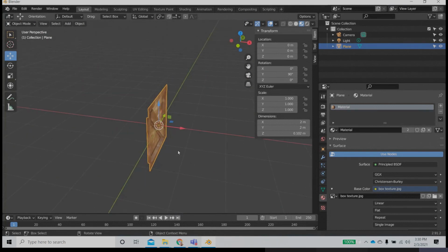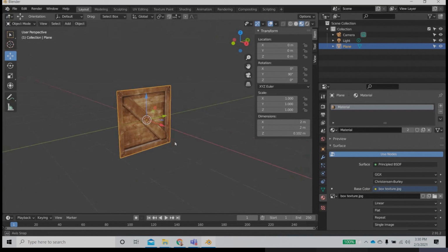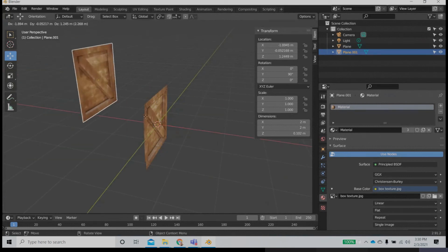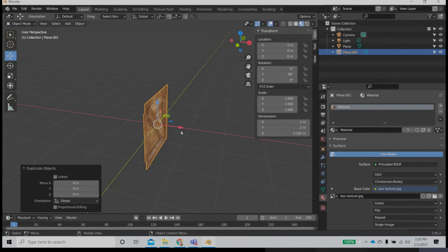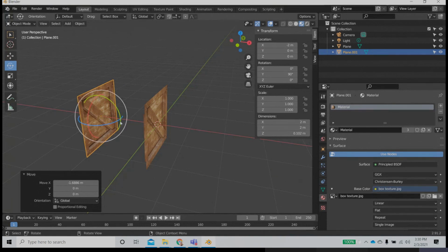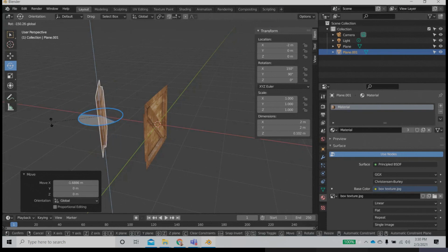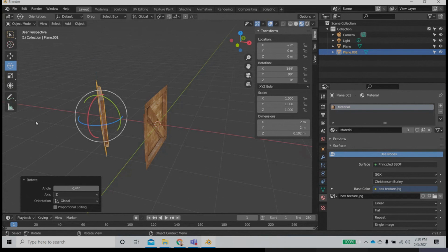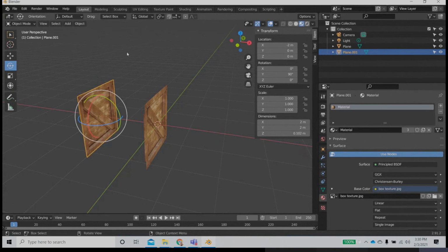Now what we need to do is create all the 6 sides from this one. So what you do is simply copy, Shift D, again right click, it goes back, you move it back, and now you know that it has to be -2 because of the size. Okay, so you just move -2, and then it has to be rotated on the other side. Okay, so you can either turn the snapping on.